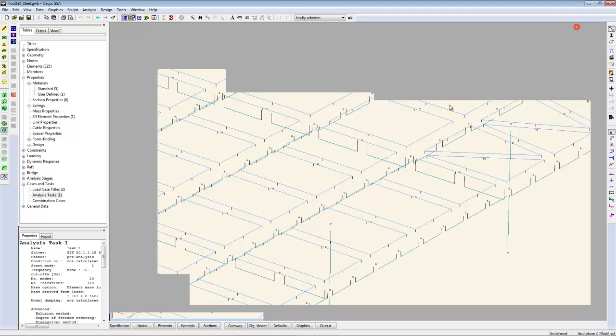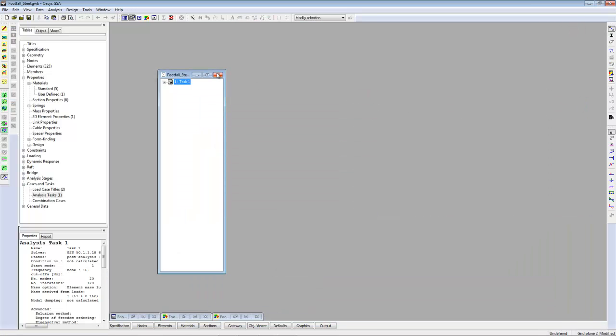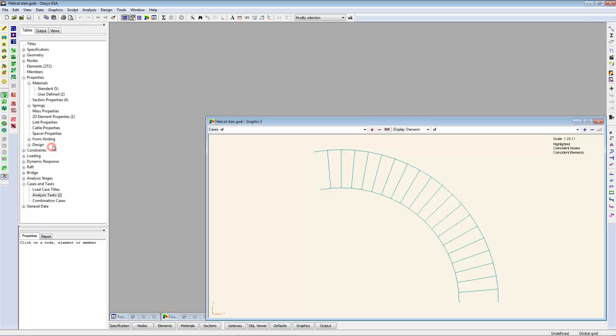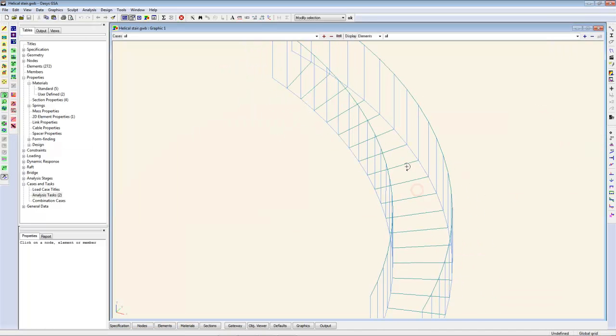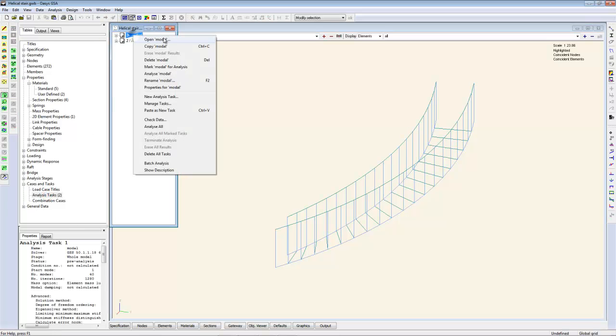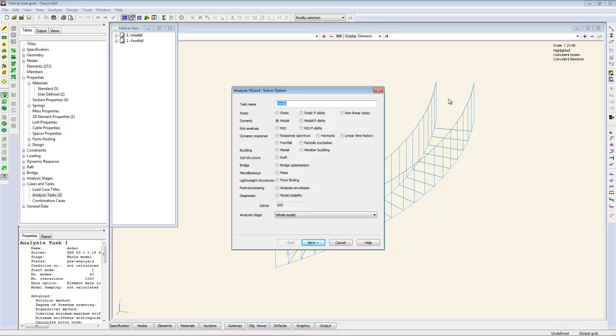Right, there's a floor. Now, with floors, of course, you only really get vertical vibration, but if we look at a staircase, due to their shape, staircases will tend to have horizontal vibration modes in there as well. Now, I've set this up so we can include or exclude the balustrading. The balustrading can have quite a significant effect on the vibration characteristics of a staircase. It's non-structural, but it does stiffen things up.